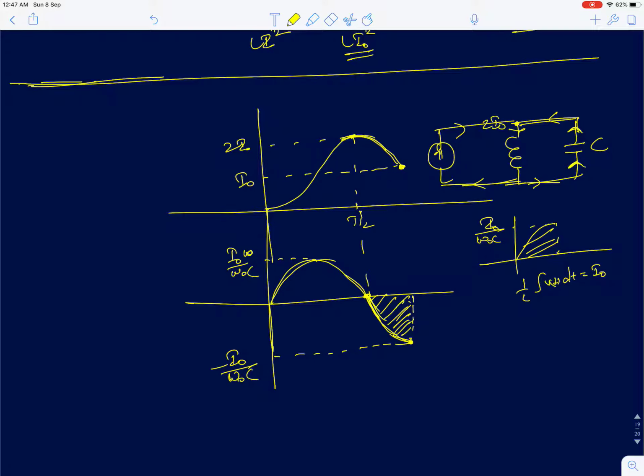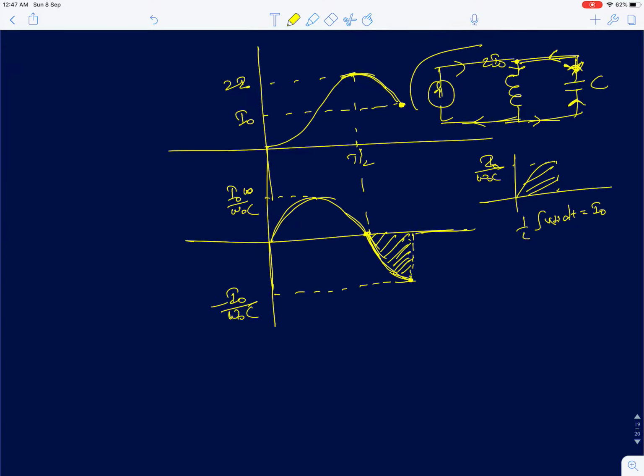And then the capacitor voltage, since it is negative again, is now at its negative peak. Now the capacitor is going to reduce the current in the inductor even more. So in this cycle, the capacitor's current will start increasing. The capacitor will now start taking current from the current source. So now I'll also draw the capacitor current.